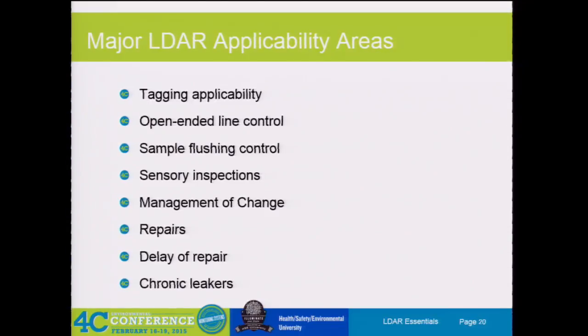There's no requirement to do it, but how else are you going to make sure that this valve gets monitored, not this one? So you have tagging applicability, which all comes in with your stream speciation data. Then you have open-ended line control. We've talked on that, and I'll make sure I get a better marker. We don't have a runner in here, or I would do it now.